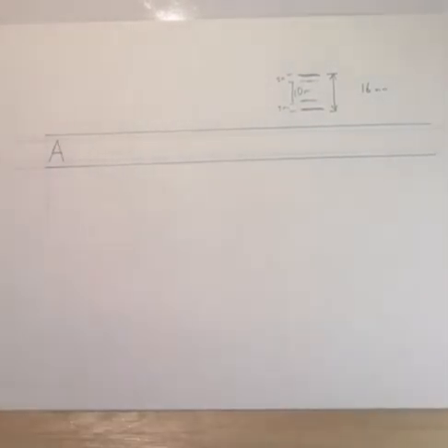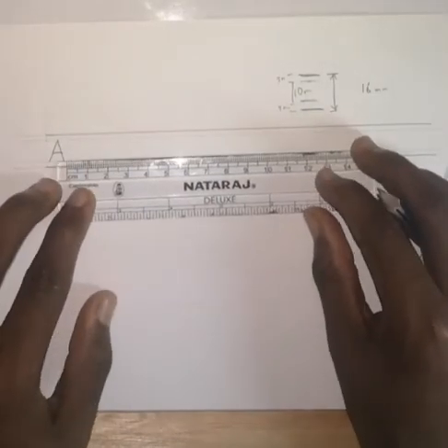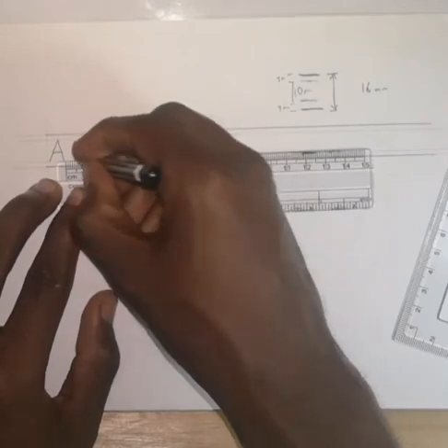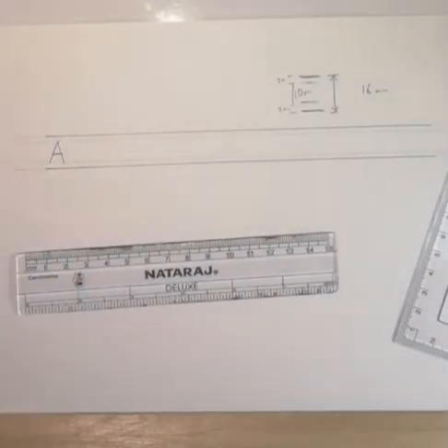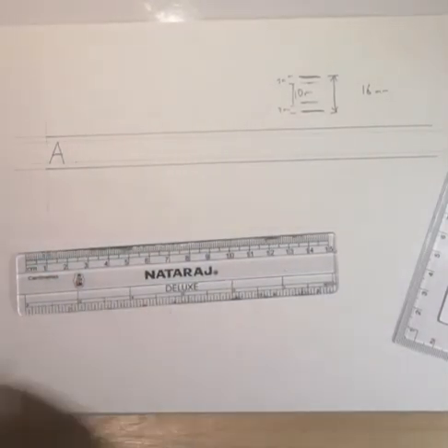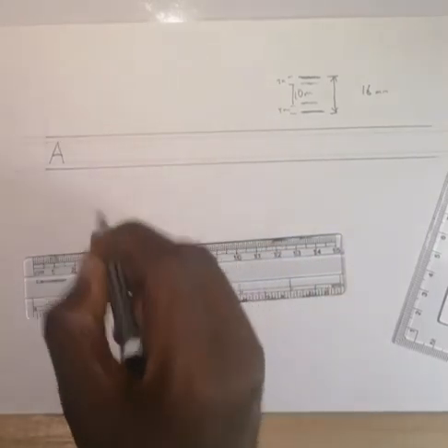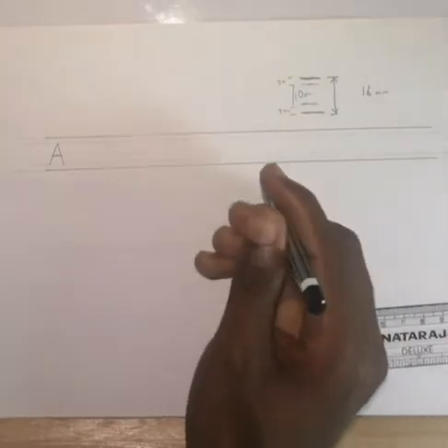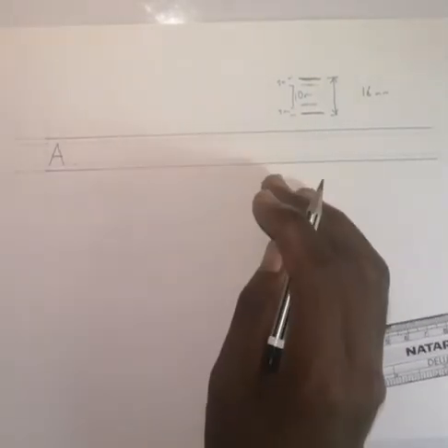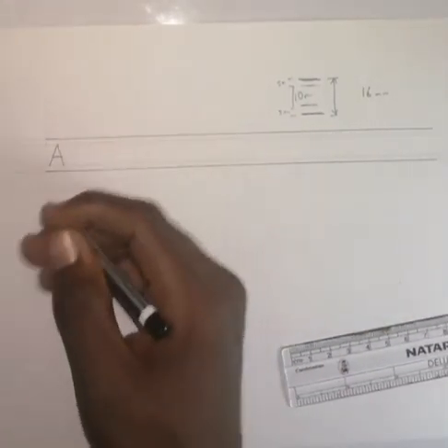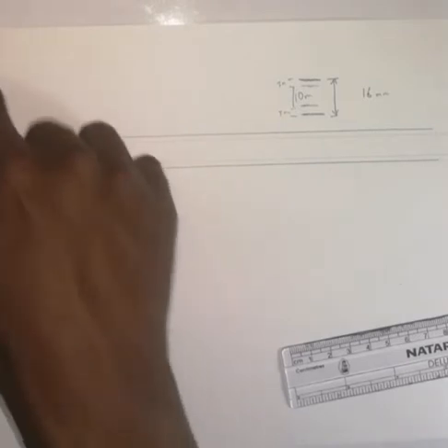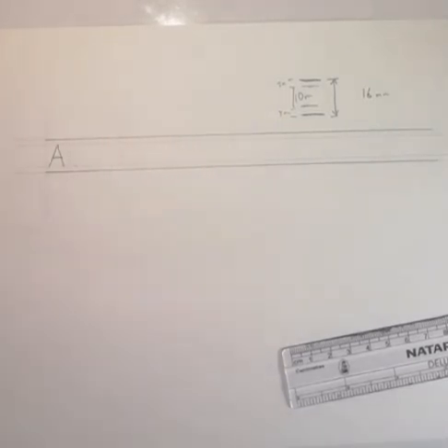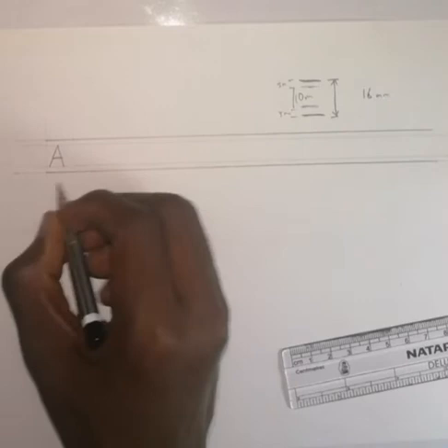So that is A, right? Then try and leave a space of roughly about 5 mm, that's 0.5 centimeters between the alphabets. Maximum 10 mm, that is 1 centimeter. It shouldn't be more, it shouldn't be less. You don't need to measure throughout. You can just stipulate, or you can just guess the distance. Just make sure that they are evenly spaced.